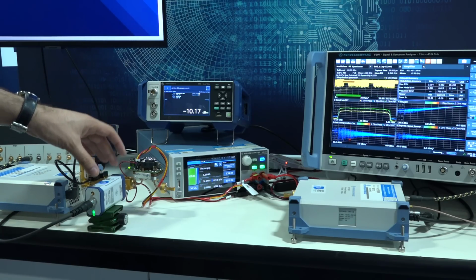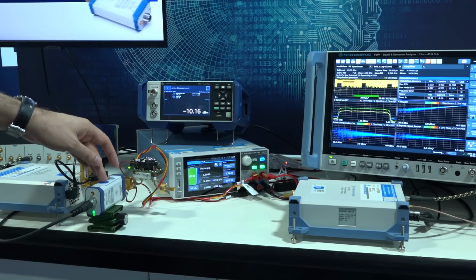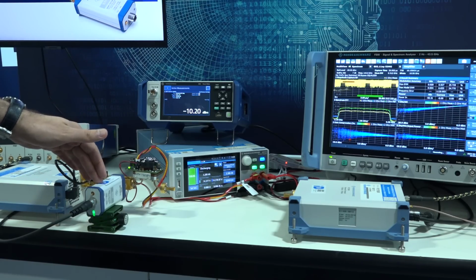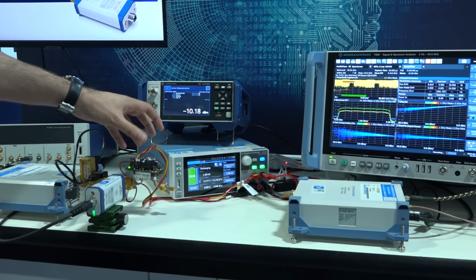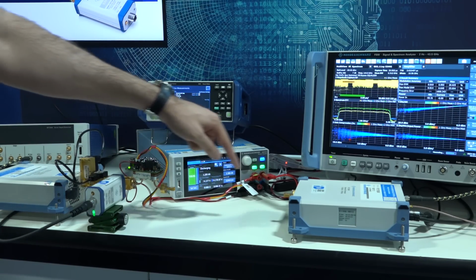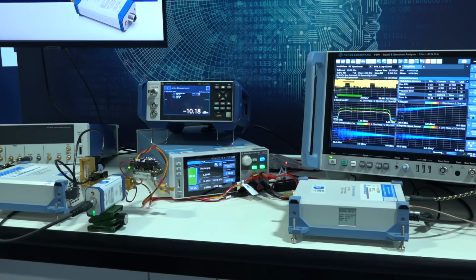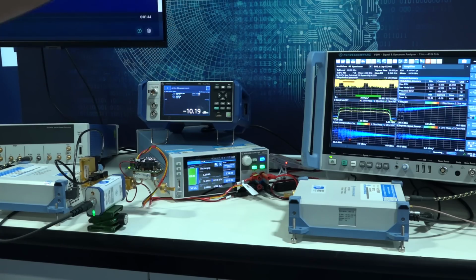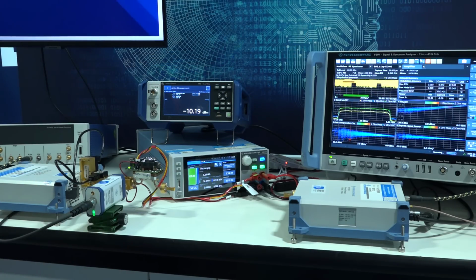This is the only 110 to 170 gigahertz banded thermal detector that has the speed and the noise floor that this particular unit provides. Then the output of that from the coupler goes into a power amplifier, and that's wirelessly being transmitted to the 170SR on the receiver. So in one setup, you have the pre-selected transmitter, the coupler, the power measurements, over-the-air measurement, and demodulation on the other end, all together in one setup.